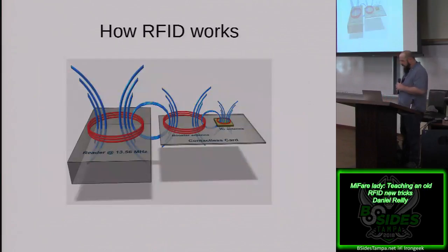The way RFID works is it uses induction. So power from the reader goes to the card. The card then uses some of that power in its internal processes, and then spits back some power as a communication channel. The inductive link is the smaller internal circle, and the communication waves are generally the larger one. The card in the example there is using 2 inductive links, but the Mifare cards actually only use 1. The chips are hardwired to the antenna in the card.